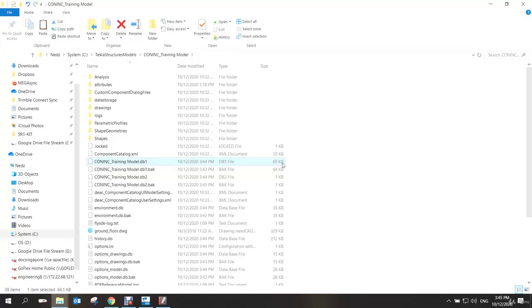This software can open really fast. Can it open a Revit file? No, it cannot open the Revit file, but it can open the IFC file, so that IFC from Revit can be opened. Vice versa, we can also export to Revit, but it needs to go through IFC. Actually, not necessary. In the new version, Tekla can export to RVT file directly, in 2020. But before, we exported only in IFC, so we talked to Revit using IFC. But now, we can export to RVT file.